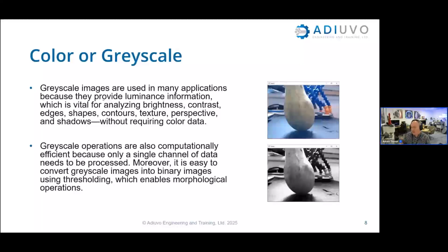So a lot of image processing might even use an RGB camera, for example an HDMI camera, like in this example, and then convert it to a grayscale image before doing the other processing. And as you'll see when we talk about why we do that in a minute in the FPGA, it can have a significant improvement, particularly in performance, by moving it into the grayscale.